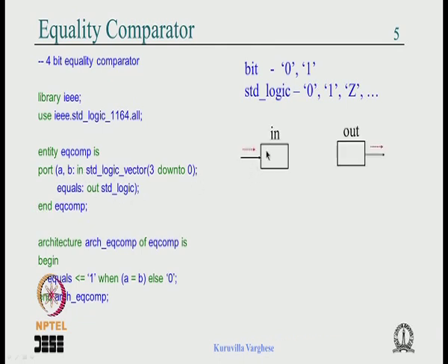In means input; the input should come on the right hand side of the assignment and cannot come on the left. Out is the output; it should come on the left hand side of the assignment. If there is a local feedback, or this output is used as input to further circuit, then you have to declare it as buffer, and only then can you use the output on the right hand side.